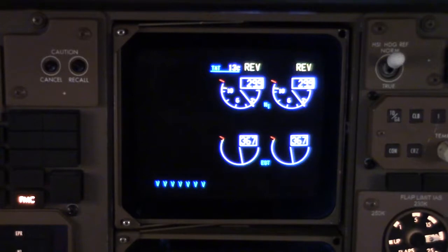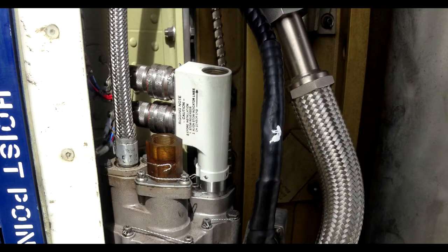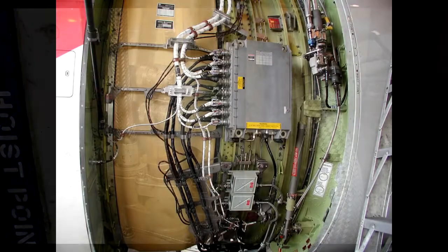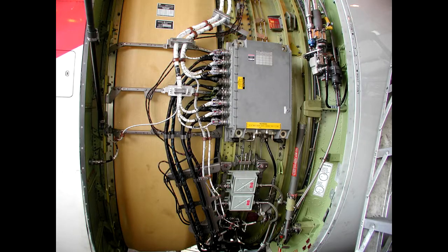This is why it's so important that the CDU position switch module, the logic module, remember, will give you the green and amber light, and it also provides the sequence logic for the actual operation that we talked about in an earlier video. The CDU position feedback transducer tells the EEC what to do.